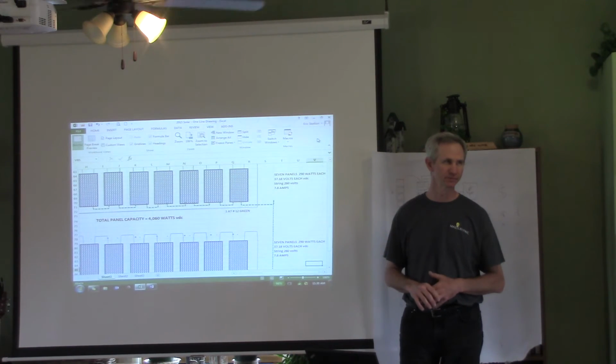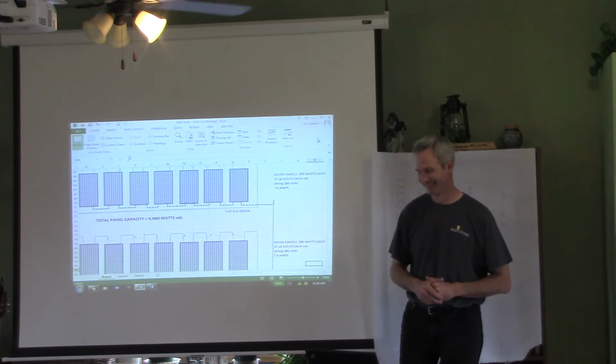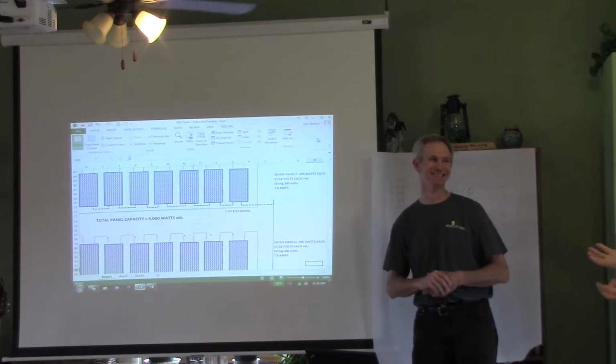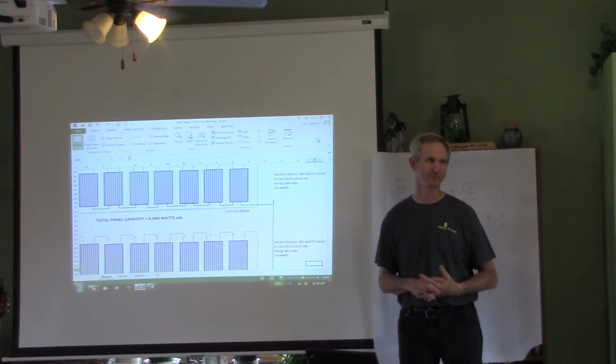The key to it though is, the same concept I've tried presenting you today: each piece has to be happy. And as you can see, there's lots of ways of doing it. There's lots of ways of making a mounting system, but each piece has to be happy. The unistrut has to be bolted at both ends. No, not just one. Why? Well, you get a hole in it, it's not gonna be happy. And as Eric started out, you have to have a goal.